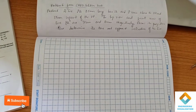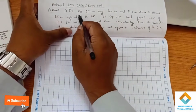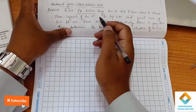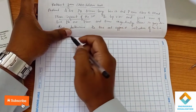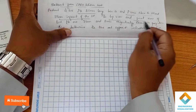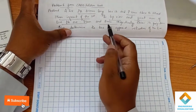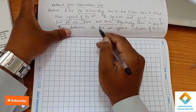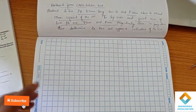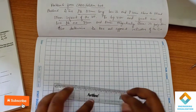Another problem from the CAD solution book, problem number 6. In this they have given line PQ, true length 85 mm long, with end P 10 mm above HP and 15 mm in front of VP. The top view and front view of line PQ are 75 and 80. So these are the apparent lengths they have given, and this is the true length 85. Using these we have to find the true and apparent inclinations.